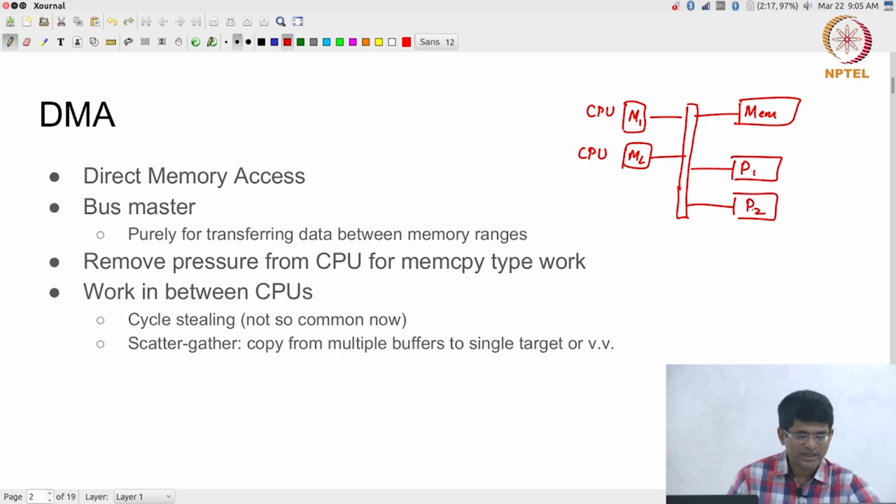Right? So now, especially with a peripheral like Ethernet or some other kind of high-speed interface, the amount of data that that peripheral needs is considerable. It's very large. If you're talking about gigabit Ethernet, you might be getting close to the point where, if you really want to continuously feed it data, one of the CPUs has to be busy on every clock cycle, just getting data out of memory and feeding it to the Ethernet interface, right?